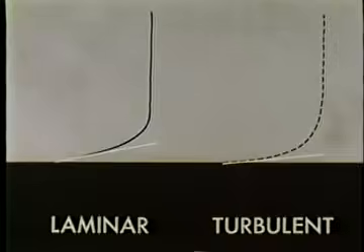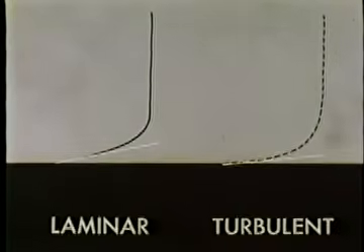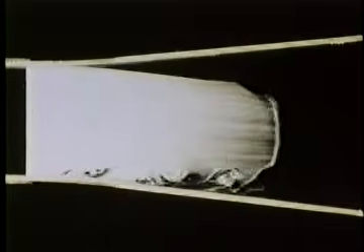In the turbulent layer, high momentum fluid is moved toward the plate, and low momentum fluid is moved away from the plate by unsteady, random motions. There are larger shear stresses and more momentum in the turbulent boundary layer than in the laminar layer, and the turbulent boundary layer is slightly thicker. In the diffuser, the turbulent boundary layer along the bottom wall does not separate, while the laminar one does, because the three-dimensional interchange between regions of high and low momentum fluid in the turbulent layer is more effective than the molecular diffusion in the laminar layer.